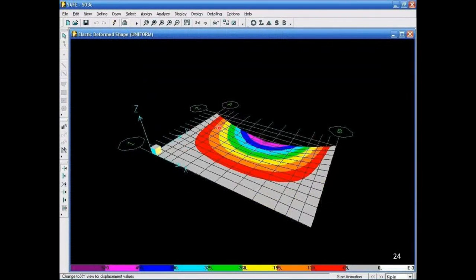Like you are doing the slab analysis in your Structure Analysis 2 project. Here we apply the load. The purple color shows more stresses here, below may be less stress, and here we don't have any stress. This is how you can plot the stresses in the slab. You can use the same model we use in our Structure Analysis 2 project and plot the stresses in that also.